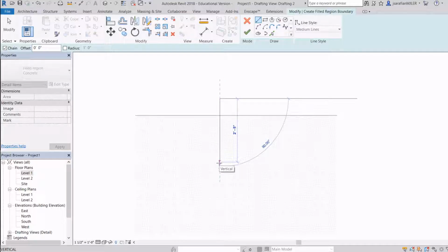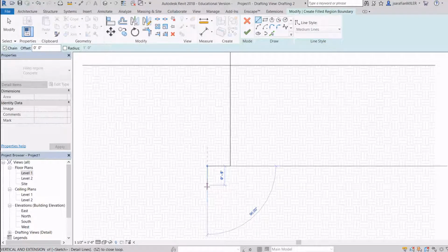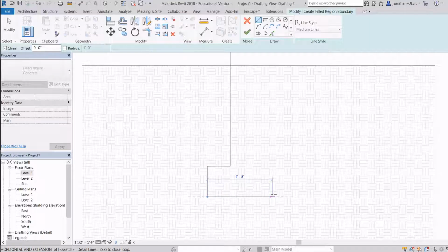We're going to keep the width of this wall to 6 inches. Depth we can adjust later, but right now I want a 12-inch thick footing. So we're going to make this 8 inches. And again, refer to local building codes for dimensions and all of this.